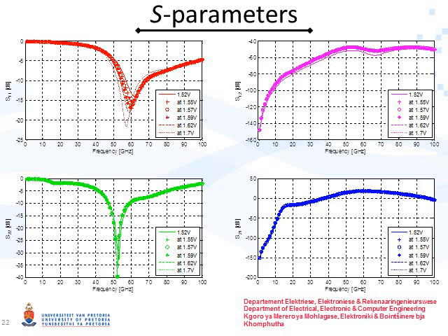These figures show the S parameters under different bias conditions. The notch of the S11 parameter varies between -14 dB at 62 GHz when the bias voltage is 1.52 volts to a minimum of -21.74 dB at 57 GHz when the bias voltage is 1.7 volts. This indicates that the input matching network remains well matched as the bias voltage increases. The S12 parameter increases slightly from -54 dB to -50.35 dB at 60 GHz when the bias voltage changes from 1.52 volts to 1.7 volts.